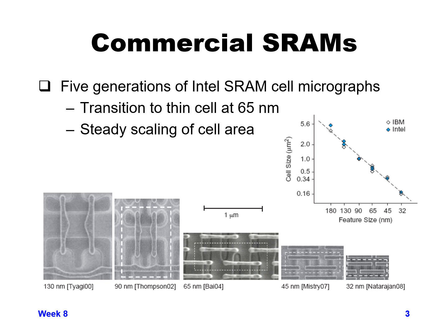technology, and that they got very steady scaling of their feature sizes and their overall cell area, on a pretty straight line graph as the feature sizes went down. You can see that both Intel and IBM, as far as the scaling of their feature size and their cell area, were very much in line with each other along that line. So the different players, even though they might have slightly different designs to their process technology and maybe to their bit cell layout, still manage to get very similar results as each other.